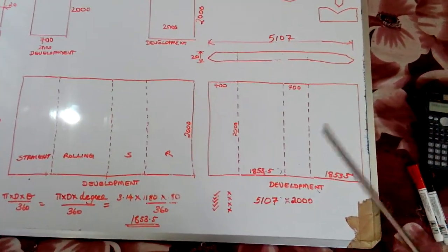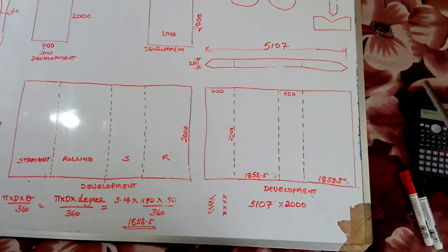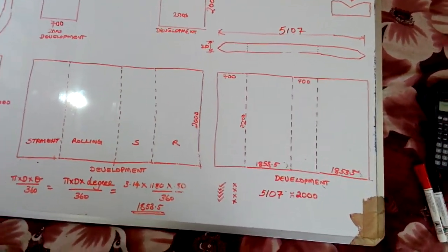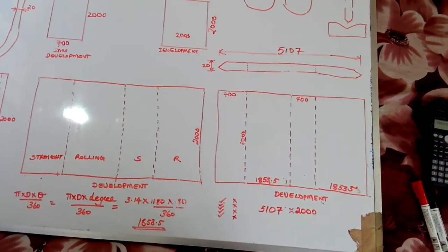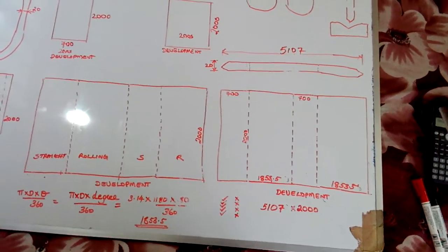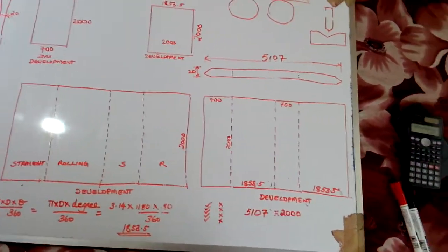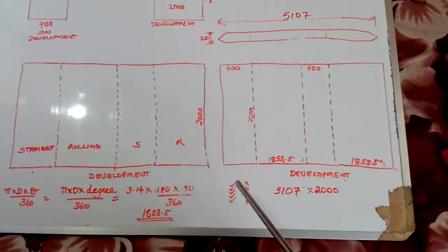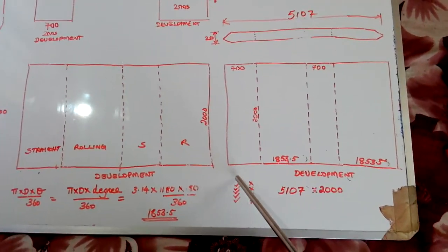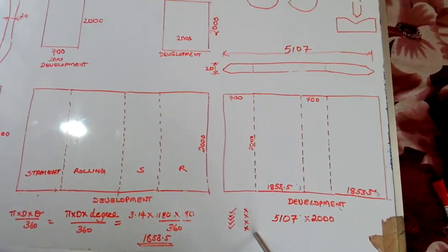We will have to use wedges, hydraulic jacks, chain blocks, gear, lever blocks, that kind of things we have to use sometimes if it has got twist. So that kind of faults are there. So if I have written so many goodnesses for this one, it is having some faults also.